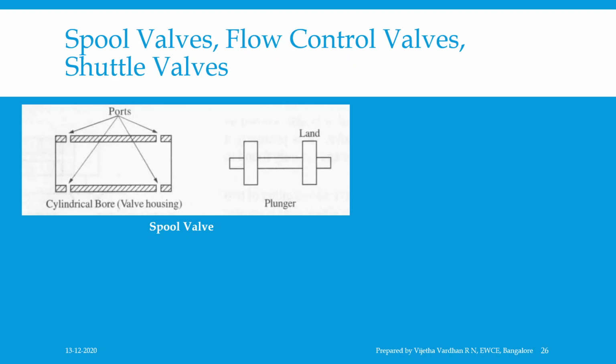The main problem associated with this type of valve in certain applications, particularly with the larger spools, is that the precision bore and fit may be distorted by externally applied loads. The problem of maintaining close tolerance may be simplified in the case of pneumatic spool valves by providing spool lands with seals such as O-rings located in grooves. But the disadvantage is that as the sealing rings slide over ports, they are subjected to cutting action and distortion takes place.